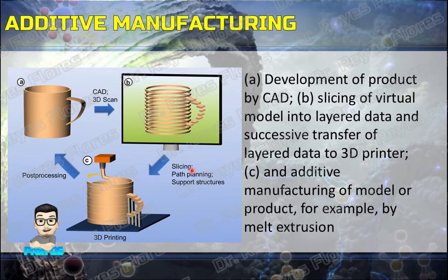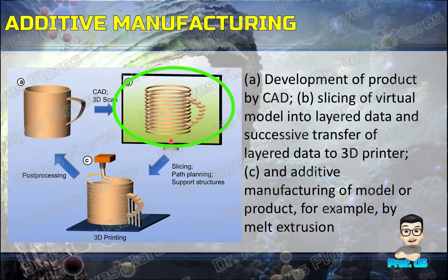In this example, the coffee mug is not very complex. It provides a convenient object to demonstrate the concepts of AM. In the first step, CAD is used to create a virtual object, which is then digitally sliced. Objects with overhanging positions are designed with temporary support structures to prevent collapse during the build process. The coordinates of the virtual object and digital slices are then used to steer the motors, which control the position of the building device or the 3D dispenser orifice respectively.